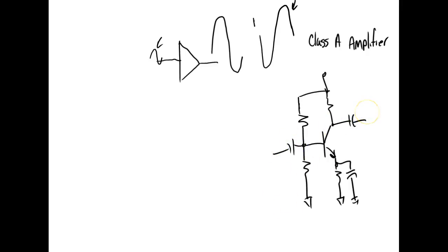Since it's on, we got DC voltages out here, so we have to have all these capacitors. But here comes in my ACC. To bias it on, to bias this thing and make it work, I've got to put a voltage right here. Or let's just say 2 volts.